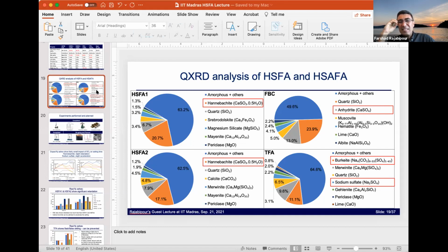If you look at exclusively pozzolanic reactivity, it is slightly lower, but there are other factors, for example the presence of anhydrite that can lead to some strength development, and that can compensate for that lack of reactivity. But overall, as I think more about this, it is an excellent suggestion to look at pozzolanic reactivity of these ashes beyond just strength activity index, maybe with the R3 test or things like that.